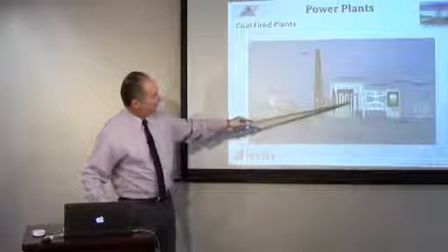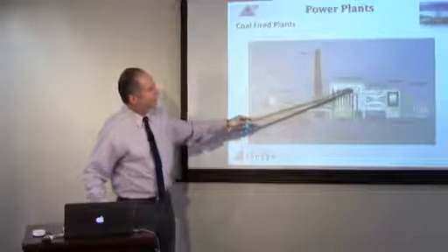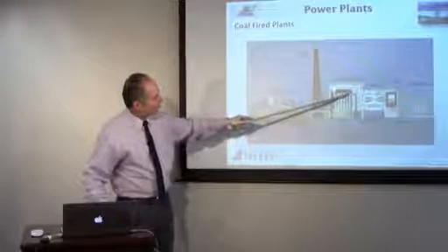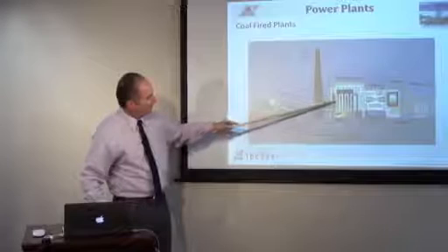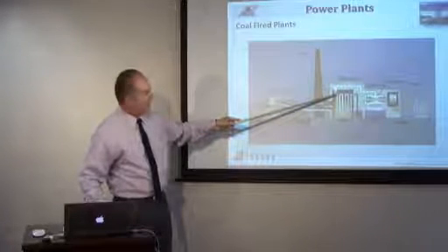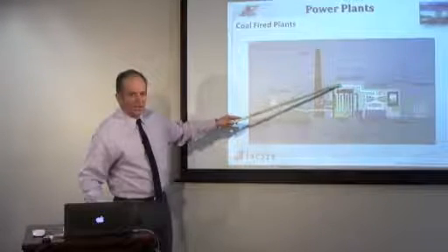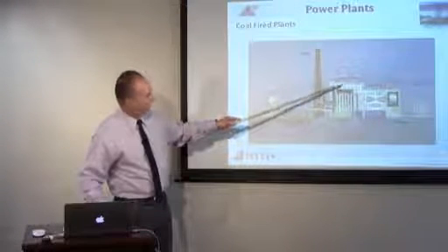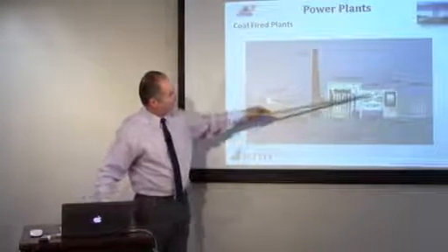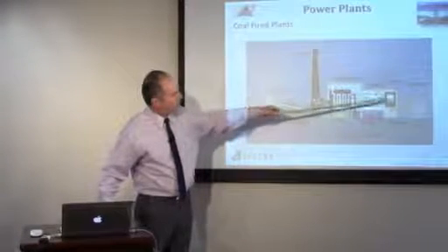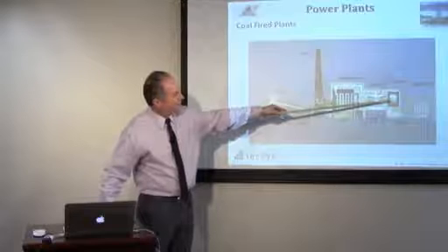which is part of the boiler system here, and we're taking water from a different system of water and we're superheating it. It's cool here, and we're superheating it to become dry steam, approximately 1,000 degrees Fahrenheit, and a high pressure, 2,000 psi. Going across the blades of the turbine, spinning the turbine, which is connected to the generator.